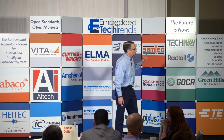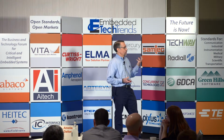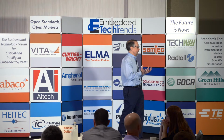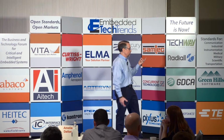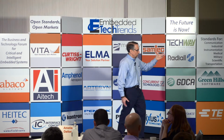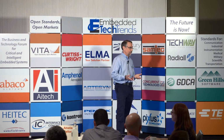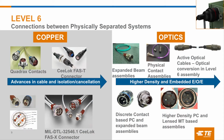When you look at where optics has trended, you see things that started as discrete solutions where you'd have a couple of discrete optical contacts and an otherwise electrical connector. That's now transitioning to those discrete contacts becoming array-based connectors because of the evolution of the transceivers. And likewise, when you look at the harnessing that you might use, again, you see a trend away from discrete connections to MT-based, ribbon-based solutions. And behind those ribbon-based solutions, again, you can have ribbon fiber, but you can also have a fairly complex optical flex circuit.